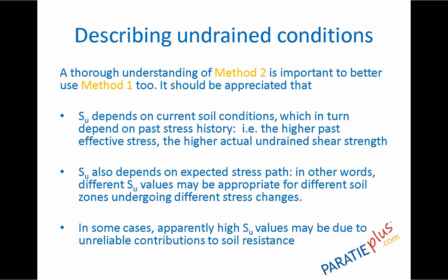Namely, it is important to remember that the undrained shear strength is not an intrinsic parameter of soil, but depends on the soil conditions in the field, and also on the geological history that the soil experienced in the past.